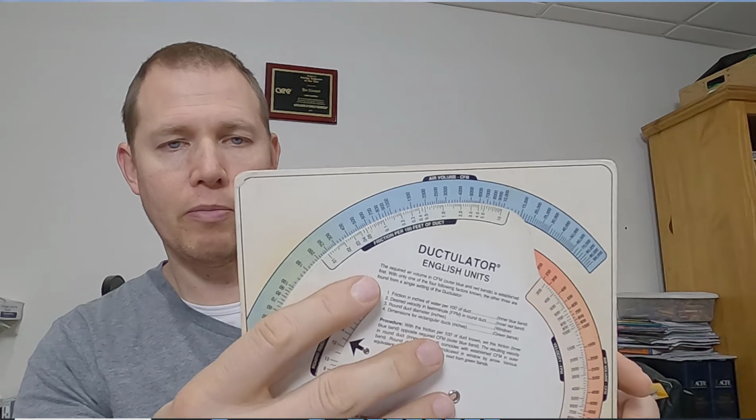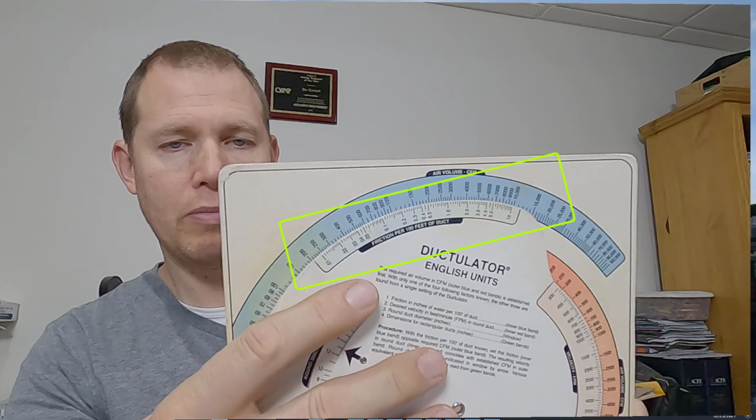about the equal friction method, and that's the one that I am going to use and the one that I typically use for modular design. It says, in the equal friction method, ducts are sized for a constant pressure loss per unit length. In other words, you pick, well, let me show on my handy Trane ductilator here. Up in the top, you pick, I'm not sure if you're able to see it, but friction per 100 feet of duct. And I normally design around a 0.06.